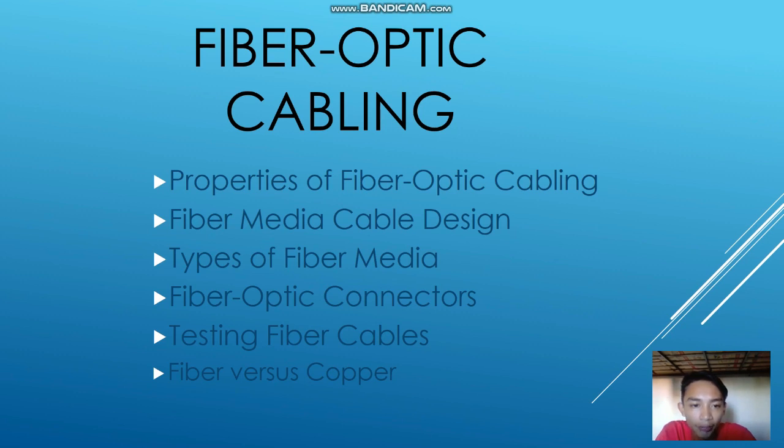Fiber versus copper. There are many advantages of using fiber optic cable compared to copper cables. Given that the fibers used in fiber optic media are not electrical conductors, the media is immune to electromagnetic interference and will not conduct unwanted electrical currents due to ground issues. Optical fibers are thin, have relatively low signal loss, and can be operated at much greater lengths than copper media. Some optical fiber physical layer specifications allow lengths that can reach multiple kilometers.